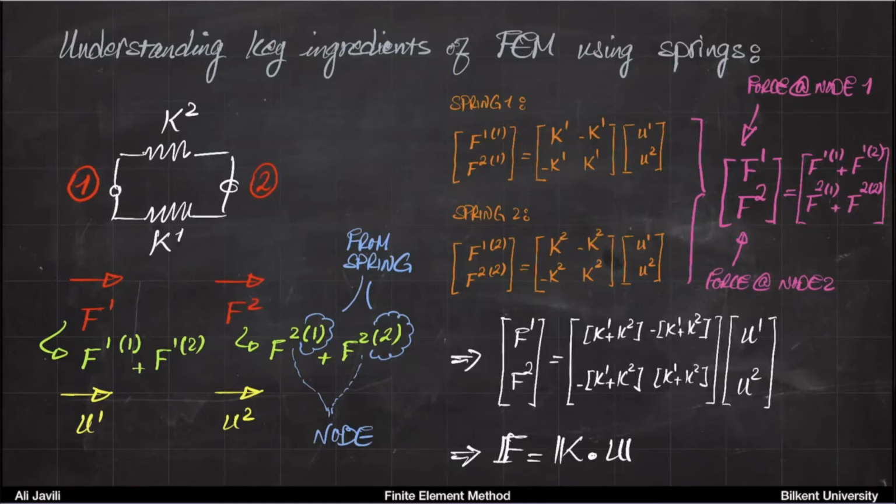But also you can see that in view of our definition of stiffness, if you think of this as being the effective stiffness of the system or the global stiffness of the system, this should have a structure which looks like K effective, minus K effective, minus K effective and K effective, where K effective is a scalar value.